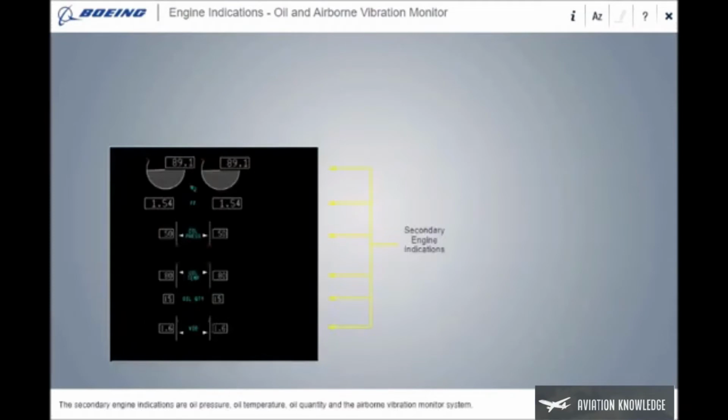The secondary engine indications are oil pressure, oil temperature, oil quantity, and the Airborne Vibration Monitor system. The oil pressure and oil temperature indications are vertical indicators with moving pointers. The oil pressure indication is shown in PSI.